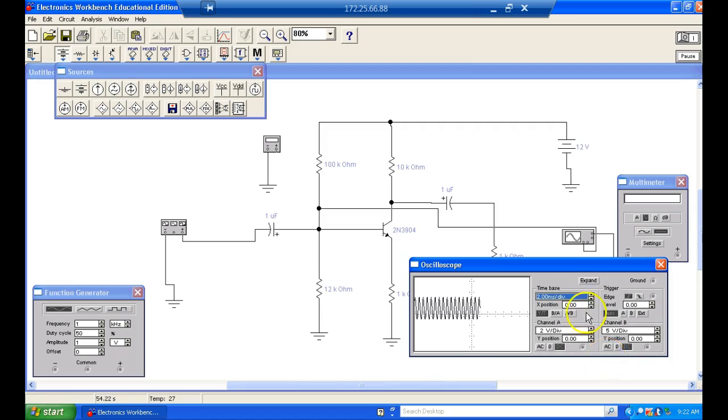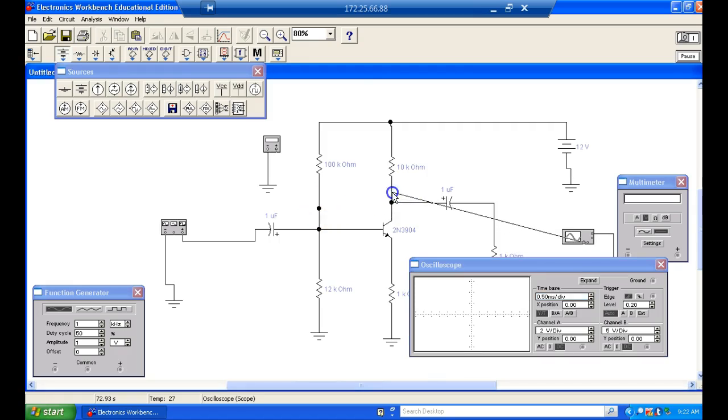And the trigger on the scope is not really good. So here's my trigger, and we got it set on 0. So here's my AC coming in. See if we can get it. Okay. Like I said, the scope is awful. So here's my AC coming in, and we have it on 2 volts per division. Good gracious. We might have to drop this down. I might have to use something else, because I think 2 volts in is going to give us problems on the output.